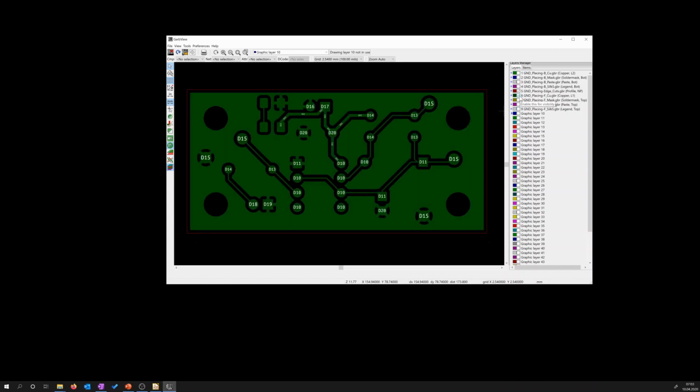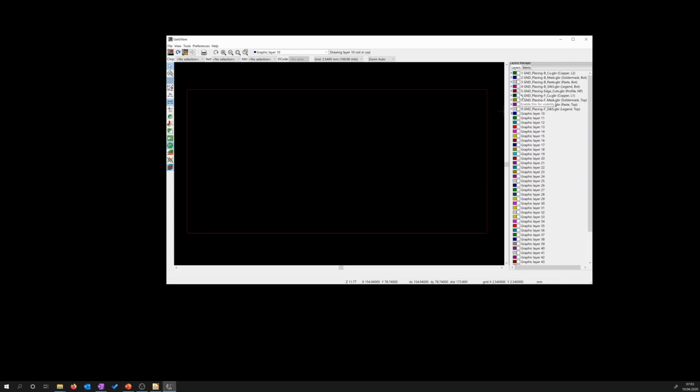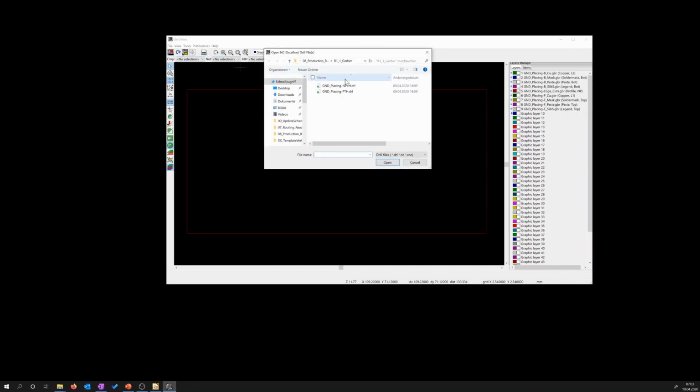Now when we have checked the Gerber files, the next interesting thing is to check if the drills are at the correct place. So the holes which are to be drilled, that's now. We go to the File menu and we open Excellon drill files. It's again in our Gerber files directory. Again we want to select all files, so we hit Ctrl A.